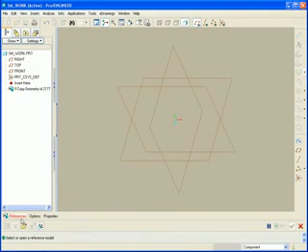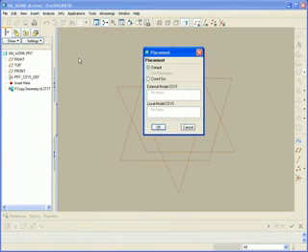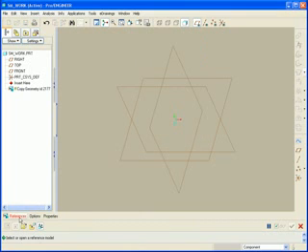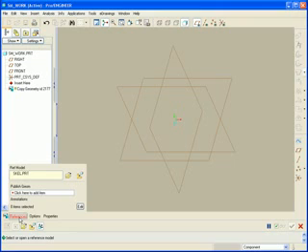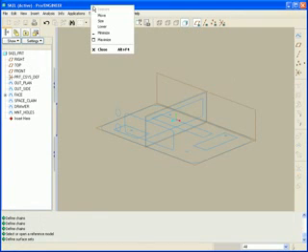So what we're going to use here is the open model and grab something that might be a skeleton. We'll locate it with respect to our part using a default, and then we'll specify what references we'd like to use. Now you'll notice here that we can only select Publish Geometry, and that's because the Publish Geometry only button is pressed. If we select that, we can then select other geometries as well.